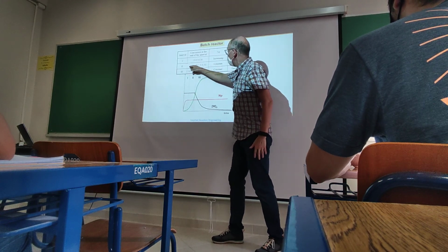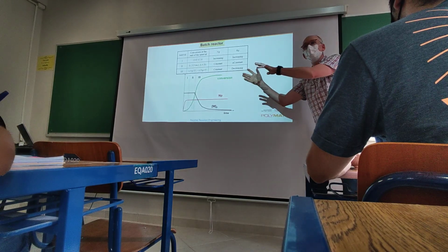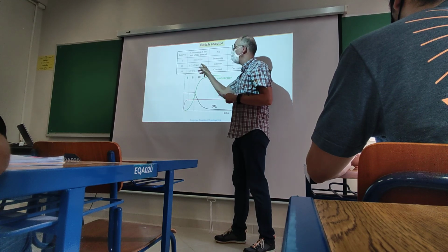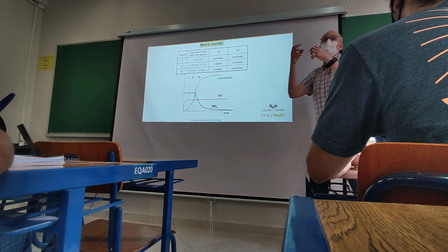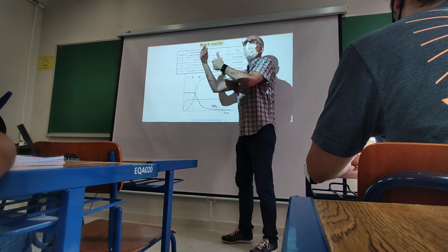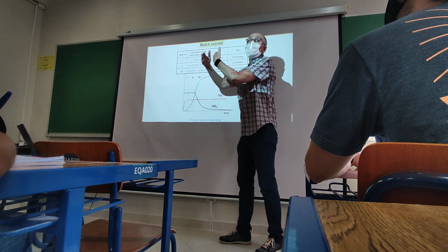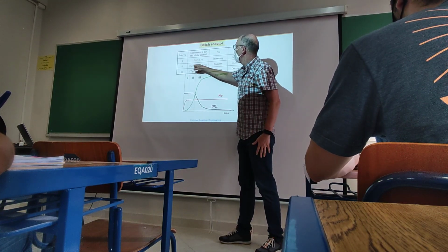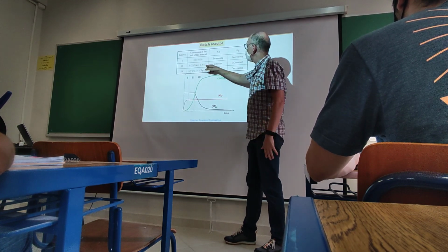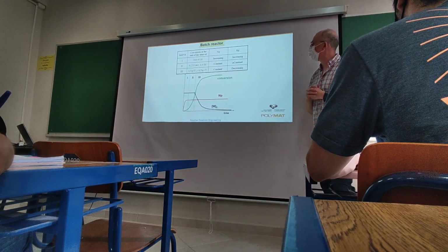And in this interval, we have droplets. And the droplets are transported to the particles. Depending on the monomer and the polymer and how much a monomer swells its polymer, the droplets might last longer or shorter. For instance, in terms of conversion, for vinyl acetate, at 20% conversion there are no droplets. For styrene, we need 40% conversion to eliminate the droplets.